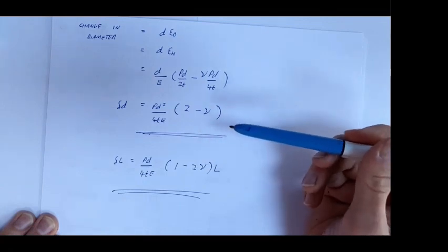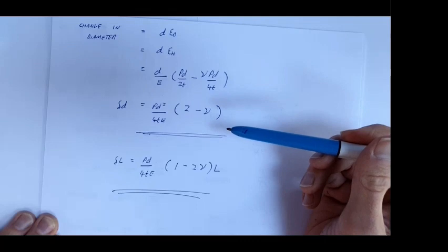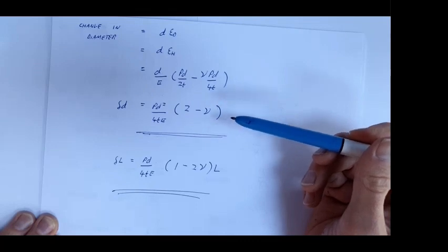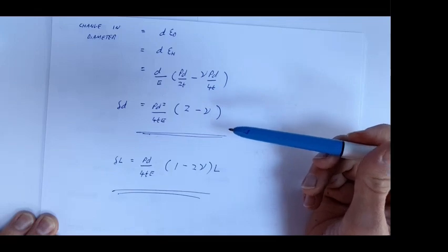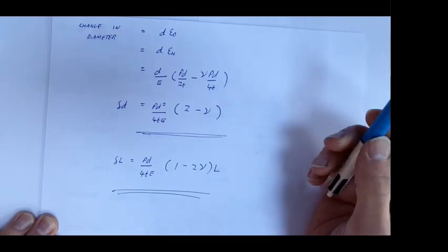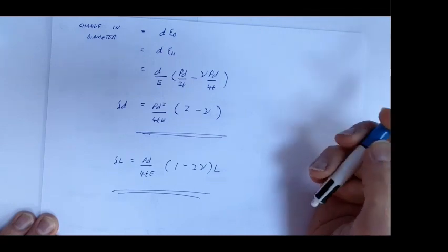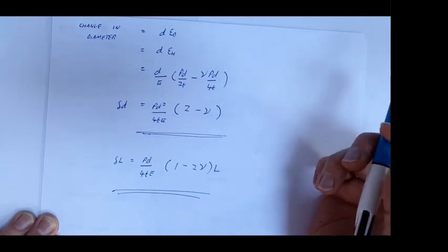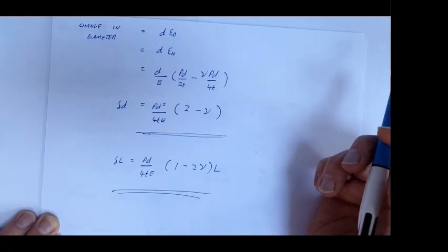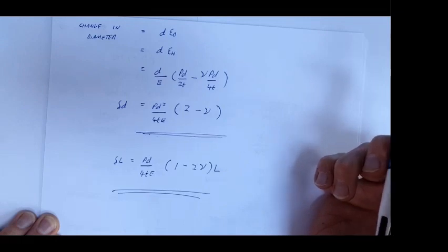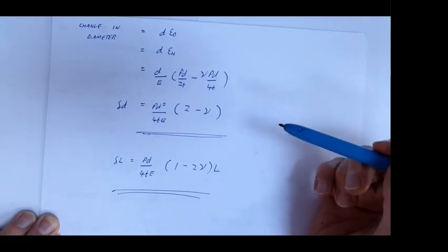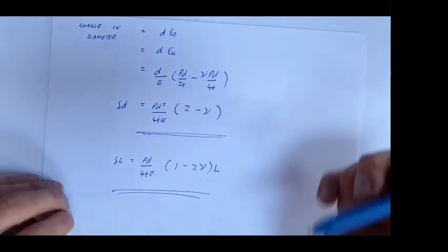Now, in order to do that, we're going to simply add 3 mutually perpendicular strains. Now that statement is true. However, it's easier to prove using Cartesian coordinates rather than polar coordinates. So let's consider something in Cartesian coordinates, which is being pressurized, and let's work out the change in volume of that. But rather than talking about diameters and radiuses and theta and so on, we're going to be talking simply about X, Y, and Z.